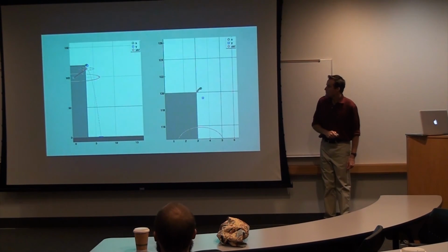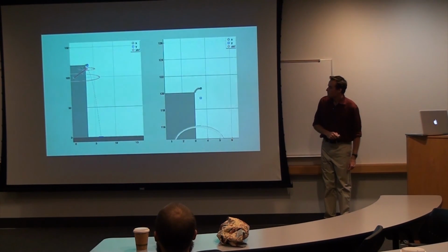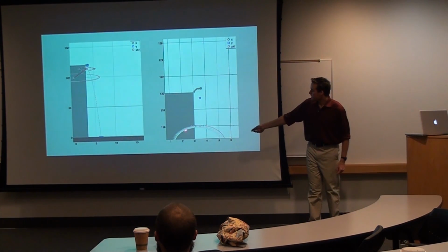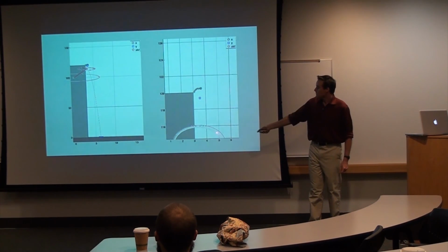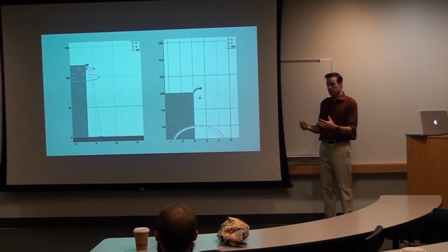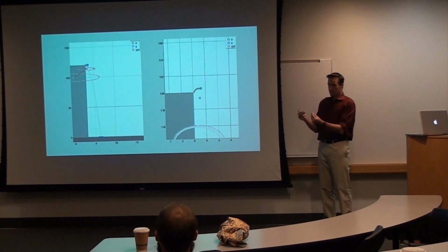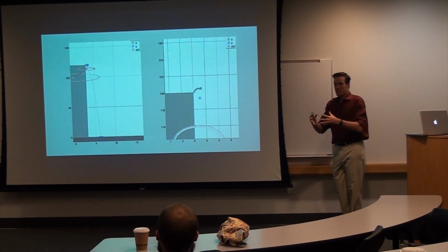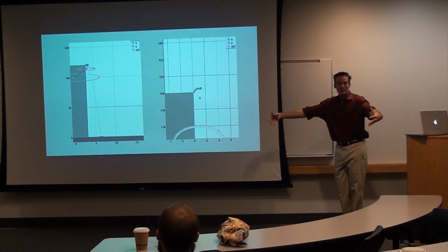And so as you propagate the system a little bit more, another thing to note here is that the estimation covariance is growing over time because the system knows that the man is being pushed around. There's a disturbance that is pushing the guy's state around, and the longer you wait and don't get a measurement, the more your uncertainty will grow.